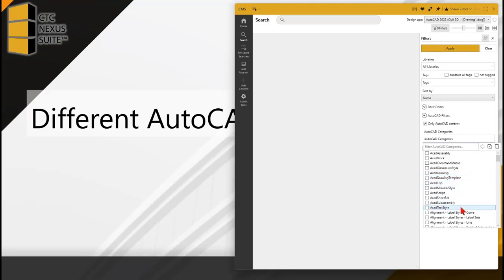You can have things like your AutoCAD scripts that you might be using, .scr files or .bat files that you might be using in your AutoCAD space. You can have sheet sets in here. There's a bunch of other command macros that you might be using on your ribbon right now in a custom CUIX file, or potentially distributing through tool palettes. You can have those command macros in here as well.